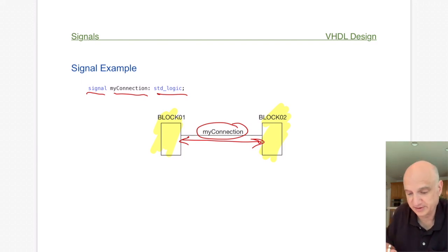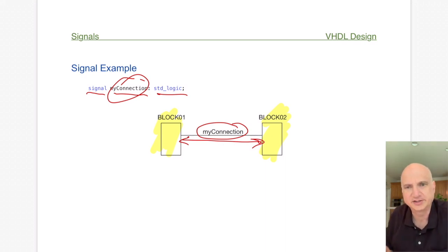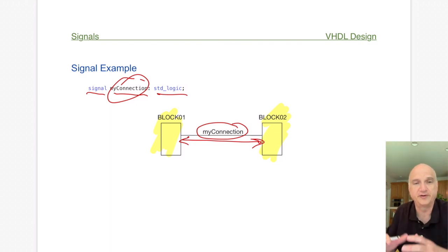We can reference this name all throughout the code when we're writing VHDL and use it for interconnecting, peeling off signals, or peeling off values for the design. So that's a very simple example of a signal. But signals can be a lot more complex than that. Signals can actually carry multiple values at one time. When we group signals together, we call those vectors.